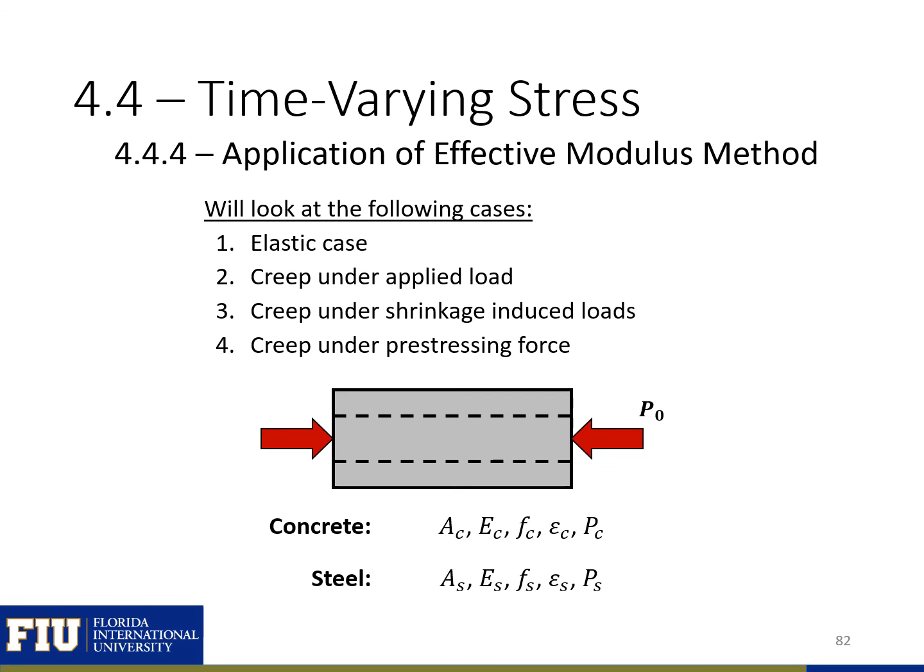In the next few slides, we're going to look at how to apply the effective modulus method to an elastic case, to look at creep under applied load, to look at creep under shrinkage-induced loads, and finally creep under pre-stressing force. We're going to have a column with an axial load applied with these concrete and steel properties.